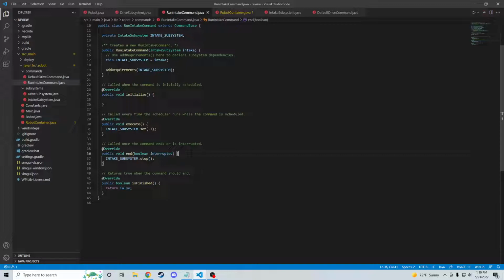I remember Sereth was telling me that on the 2019 robot, they knew that their elevator was at the top of its extension when the current draw was really high, because it took a lot of force to get it to break. You'd physically be bending the robot at that point. So when you knew the current was high, you knew that it was doing something it shouldn't be doing, so you'd stop the robot.